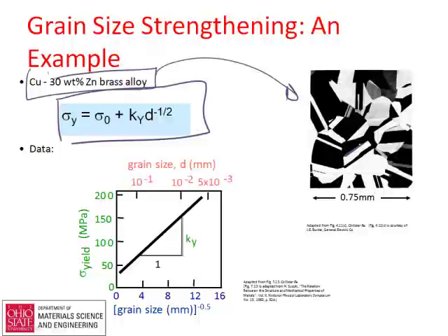These are twin boundaries, these flat boundaries where you see contrast, and all that contrast comes about by polishing the material, splashing a little bit of etchant on it, and splashing is maybe a little flippant, but getting just the right amount of etchant on it the right way, you can pull those things out and then look at the optical structure of the material.